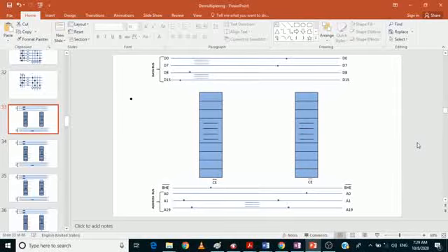So here, let me take one simple explanation for your convenience. I'm not going to take much time for this. Let us suppose I have a 4-bit address, so we have 4 address lines. 4 address lines means how many combinations are we going to get? Obviously 16 combinations. 16 is a little bit difficult, right? I'll take 3. Let us suppose we have 3 address lines. How many locations are there? 3 address lines means we are going to get 8 memory locations.